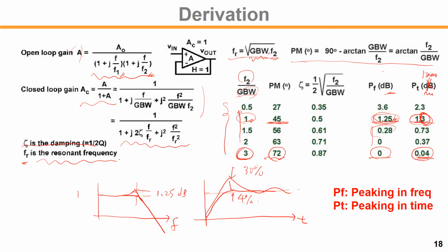This is the dB scale. Oh no, this is all the linear scale, I guess. So if you have around 45, you get the 25% larger peaking, meaning what? Around 3 dB peaking. Around that, 30% larger peaking corresponds to the 3 dB, right? So as you can see in this example, you definitely want to design the loop in this condition at first trial. Okay.